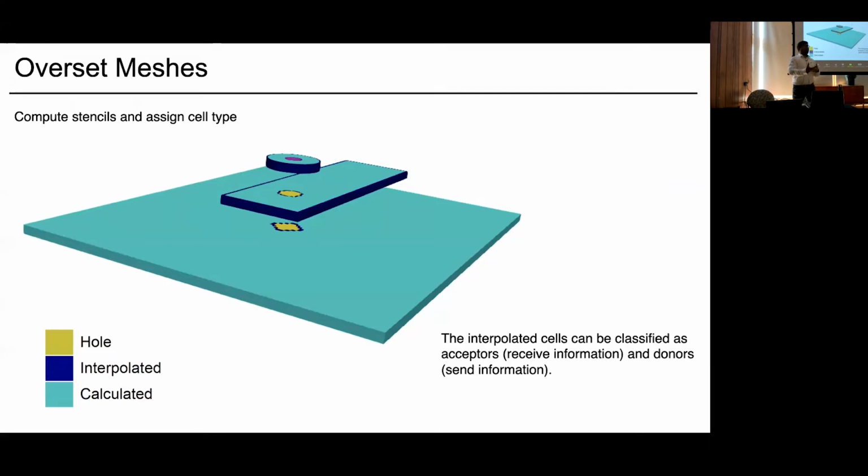One overset mesh connects with the refinement zone, and then the refinement zone connects with the background mesh. There the interpolation takes place, and the very important thing is that the size of the cells in this interpolated fringe should be similar to reduce the interpolation errors. Otherwise, the errors will be very high. And then in the other colored area, where you can see the green color, they are all computed regions.